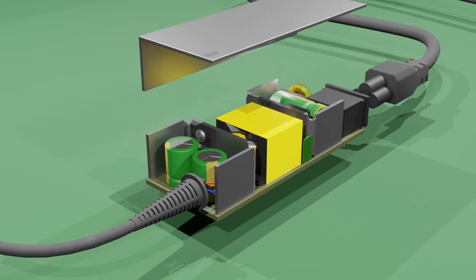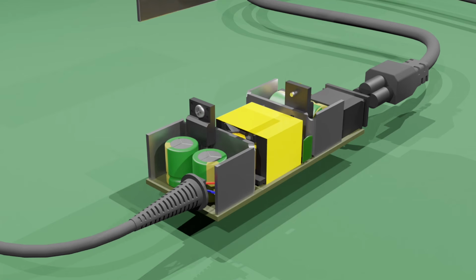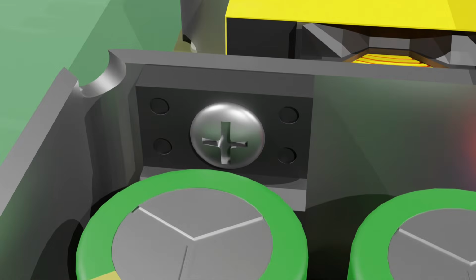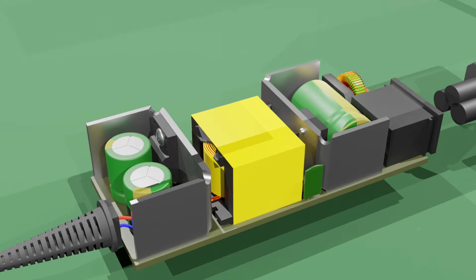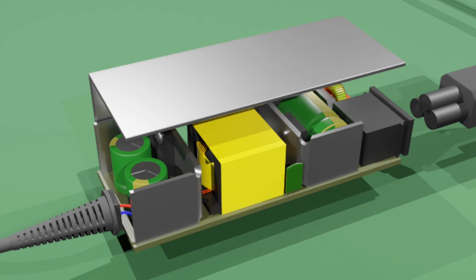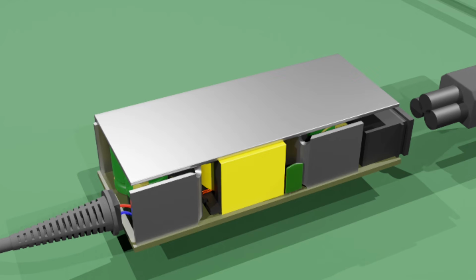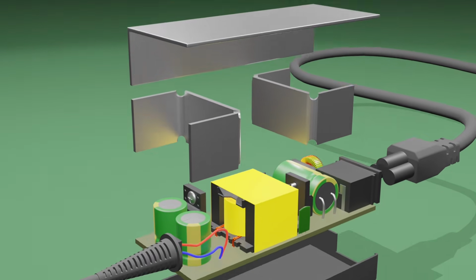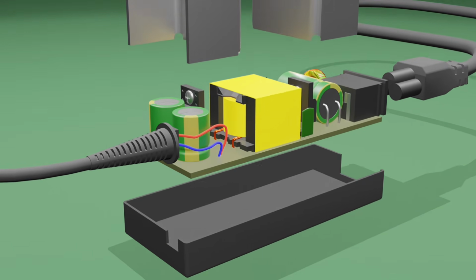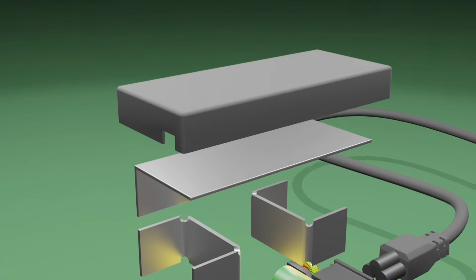These switching components generate a lot of heat. Thus, the MOSFET and the dual diode are bolted onto large metals. Take a look at the one here. These metals are then glued together with the transformer onto a larger metal sheet that conducts that heat onto the plastic casing, keeping everything somehow cool. To the components inside, it's actually cool, but to your hand, that might not be the case.